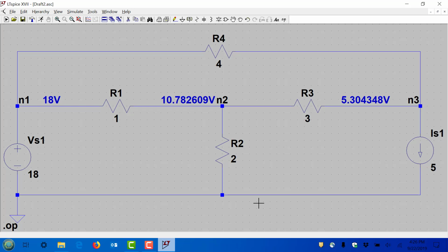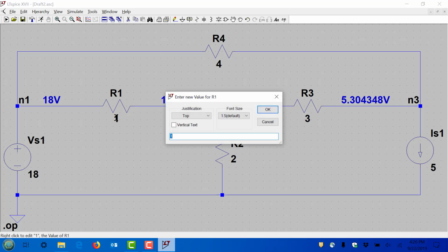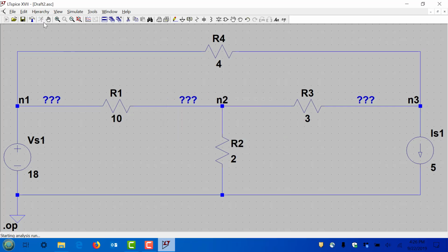Okay. You can do the same thing with a resistor value. Oh, I don't want 1 ohm here, I want 10 ohm. Right click on the 1 ohm, change it to a 10 ohm, right? OK it, and then I have to rerun the simulation. Rerun the simulation, okay? And then you get these values. And you see over here you get millivolts, which means 10 to the minus 3 volts. So you have something like 307 millivolts, which is the same as 0.307 volts approximately in this case.